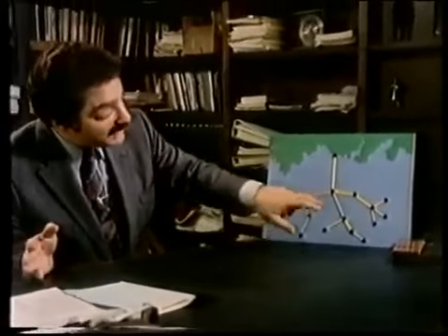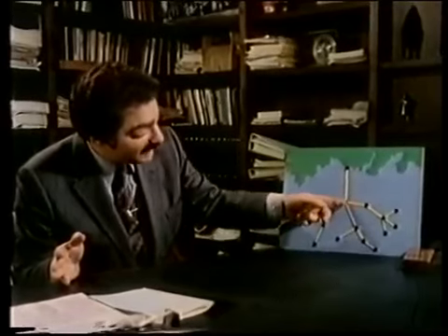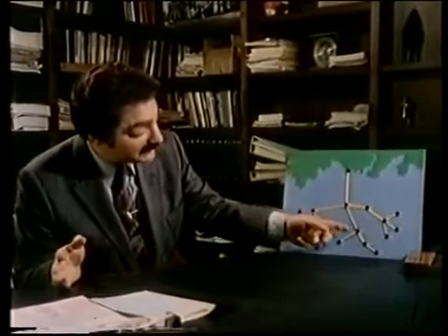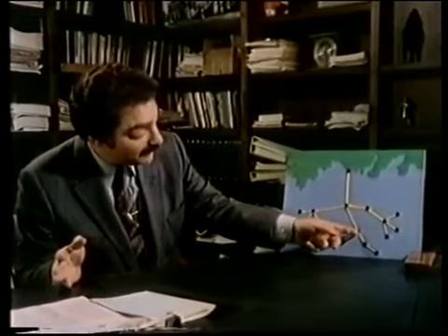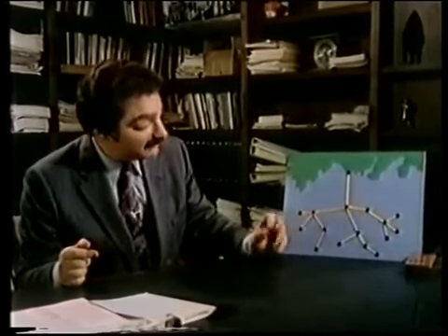That is, what is the proper arrangement of pipelines in terms of locations? For example, I have a pipe going from here to here. I could just as easily have made that pipe be replaced by one going from here to here. Selecting the right topology, that is the right configuration of pipes, is itself a difficult problem. If you can't solve the first problem, then you clearly can't solve the second problem. So we decompose the problem into two separate problems. First, the design of the diameters. Second, the actual design of the configuration of the network.